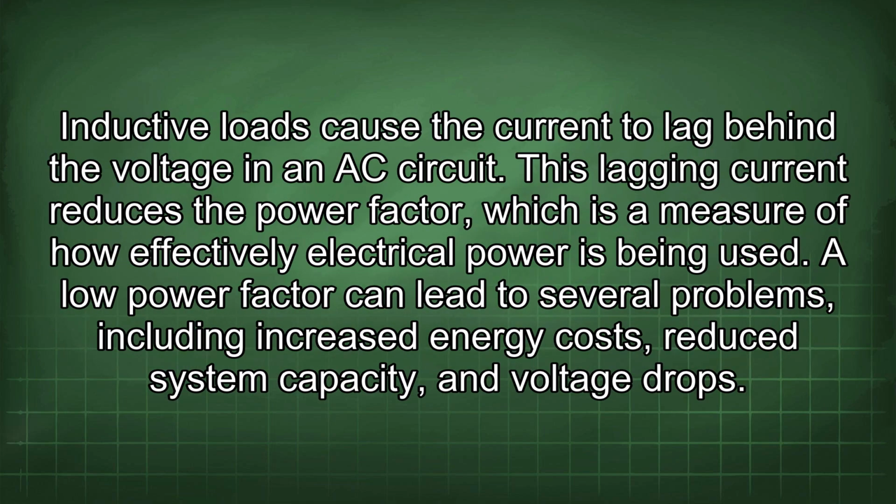Inductive loads cause the current to lag behind the voltage in an AC circuit. This lagging current reduces the power factor, which is a measure of how effectively electrical power is being used. A low power factor can lead to several problems, including increased energy costs, reduced system capacity, and voltage drops.